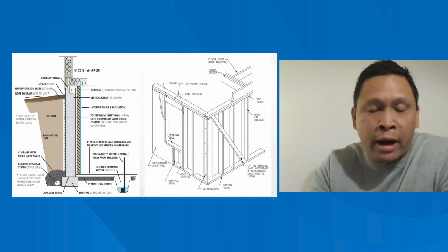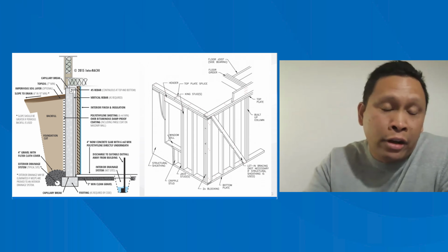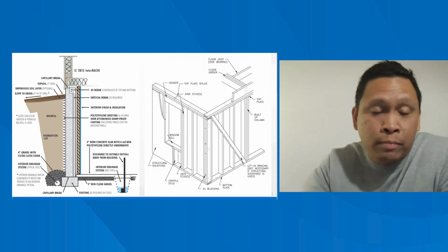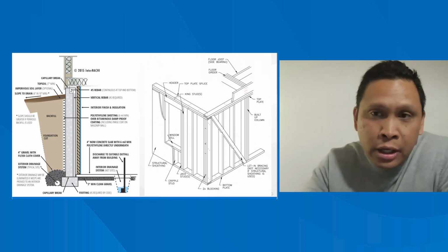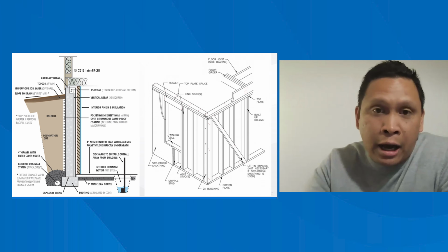They'll rack their brain all around the HVAC system trying to determine why it is creating so much humidity. But one of the difficult parts is, can anyone determine if the entire foundation is actually sprayed with damp proofing? No way to know. So that's why it's so important to advocate for a foundation inspection.